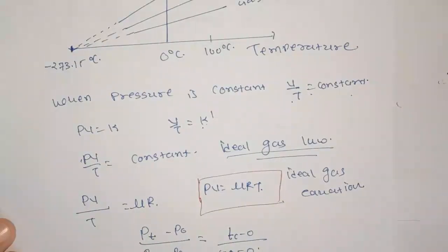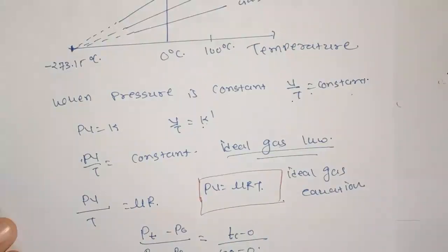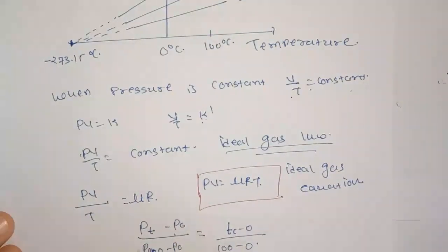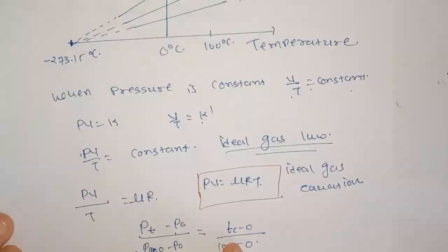In one type of gas thermometer called the constant volume gas thermometer, the volume of the gas is kept constant and the change in pressure of the gas is used to indicate temperature. By placing the thermometer in ice water and water steam baths, the pressures measured are P0 and P100 respectively. The interval between P100 and P0 is divided into 100 equal intervals.